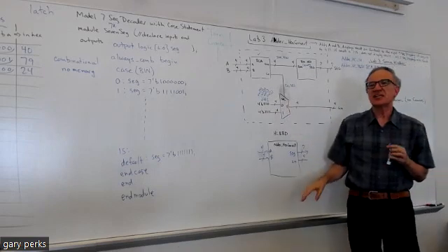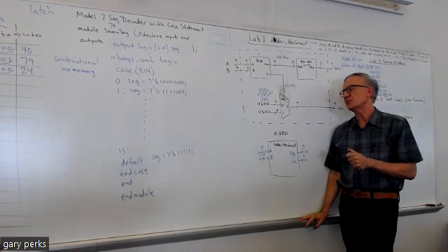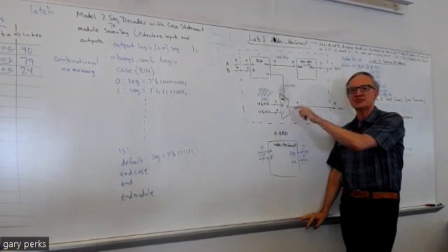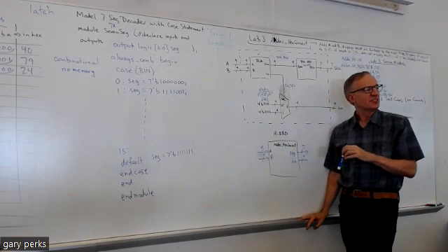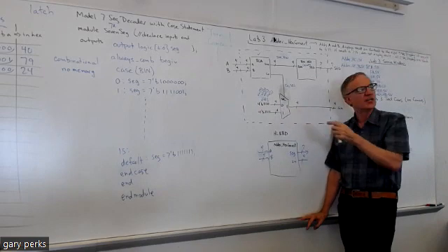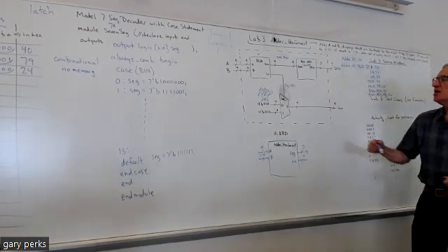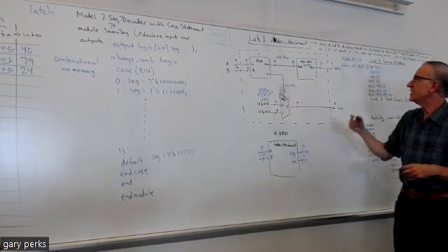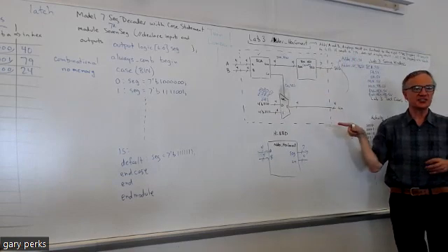Now, one other thing, and again, I'm not 100% sure on this, but I don't think Vivado likes it when you name inputs a number. Like I wouldn't name this input 0 and this 1 like I've written on the diagram. I just did that for space reasons because I didn't want to spell out 0 and 1. But when you actually do this, I would write out 0 and 1 or use some other letters for those inputs. But where you make these connections of the mux inputs to the data is in this file here,